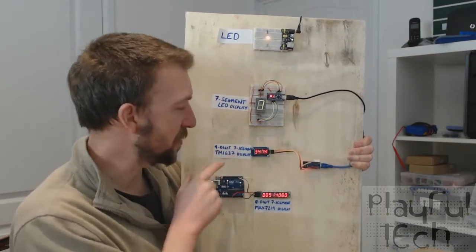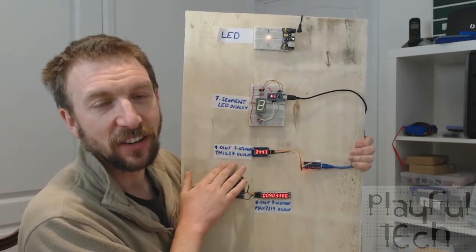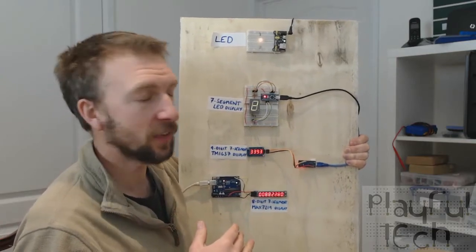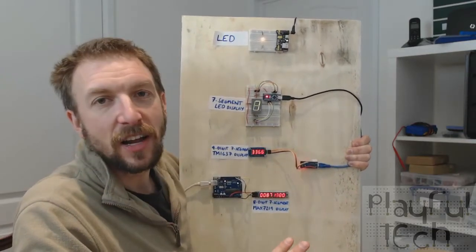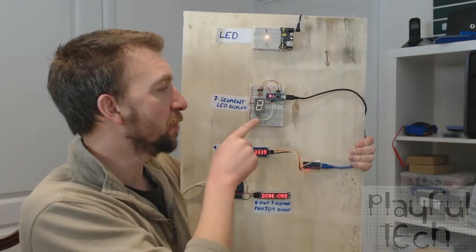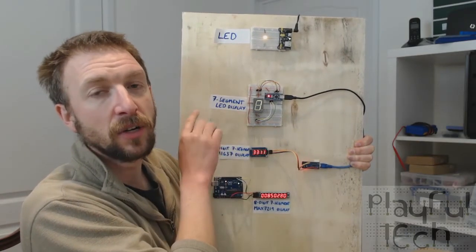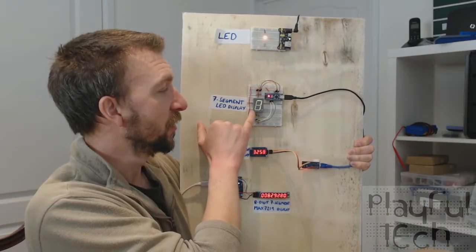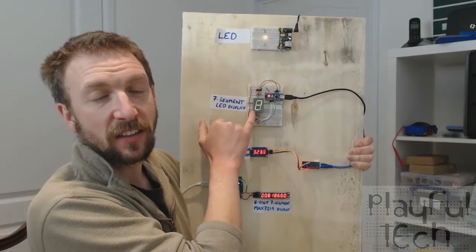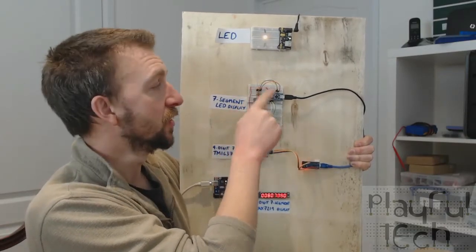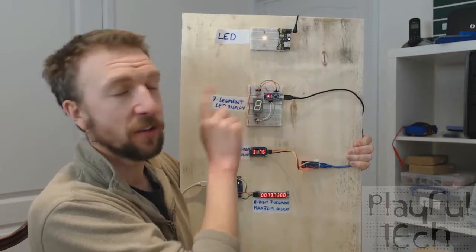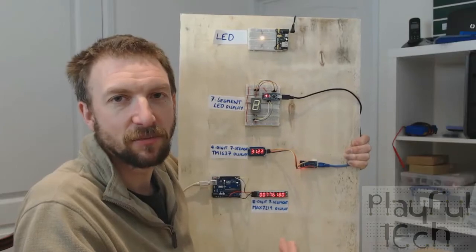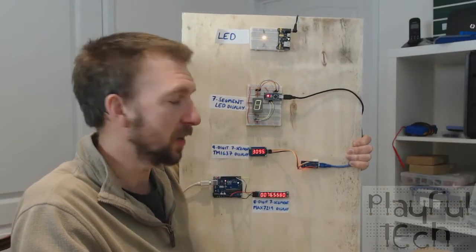Okay, now we move on to the 4-digit display. So we're getting a bit more useful now, because you can actually do slightly more when you've got more digits available to you. It might have become obvious that if you simply put 4 of these in a row, you're going to have quite a job wiring it and controlling it, because just one digit like this is going to require 7 cables for each of the 7 segments, and also the common pin. So if you're trying to wire 4 like this, that's going to be 28 leads, which is going to be rather a nightmare to wire.